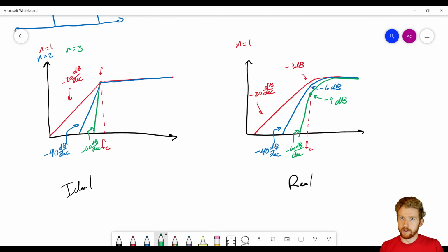So this is something that you have to consider, that your minus 3 dB point is going to change for these second order filters if you do it this way. That's why I've tried to really drive home that for these higher order, more complicated filters, what you're going to want to do is simulate them, because it's harder to figure out on paper what that frequency response is going to look like. Okay? So that's the message of today, is that these bandpass filters, it's good to have an intuition of how they work. It's good to have an intuition that it's just 2 filters in series. Same thing for these higher order filters, but really in practice you're going to want to simulate them before you implement anything.